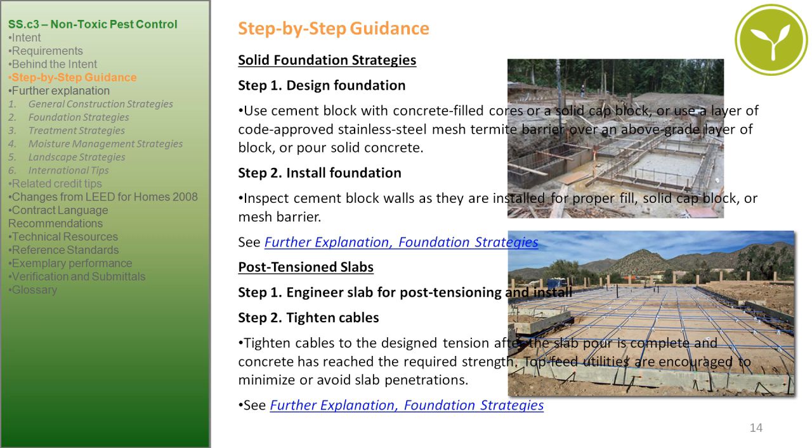Post-tension slabs. Step 1. Engineer slab for post-tensioning and install. Step 2. Tighten cables. Tighten cables to the design tension after the slab pour is complete and concrete has reached the required strength. Tap feed utilities are encouraged to minimize or avoid slab penetrations. See further explanation, foundation strategies.